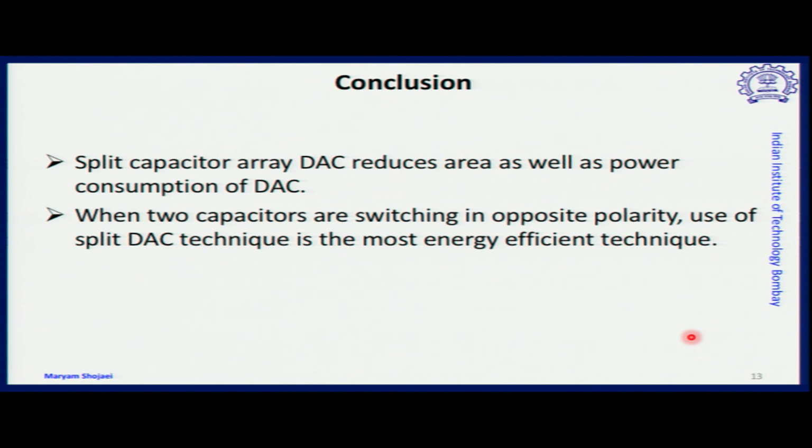With respect to binary cap switching, we learned three different methods of switching as compared to the standard switching, which helps us reduce the extra energy consumed from V full scale due to the switching of opposite polarity capacitors.